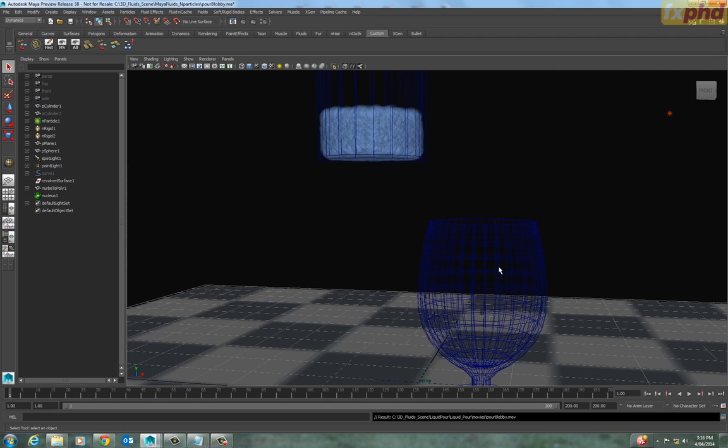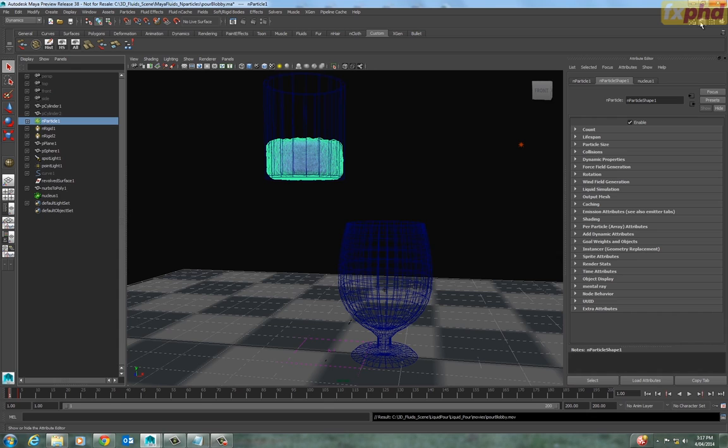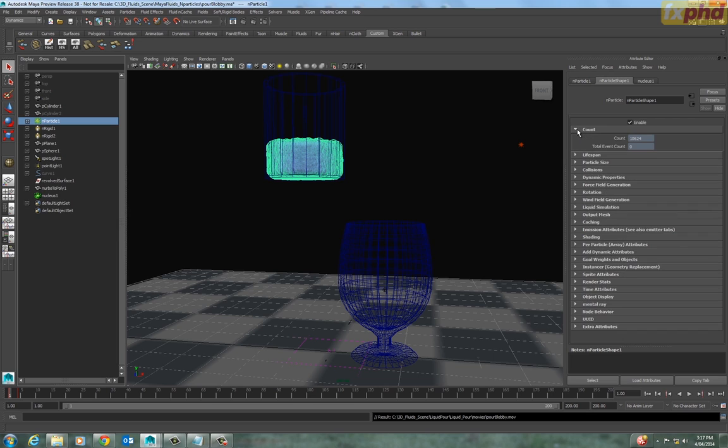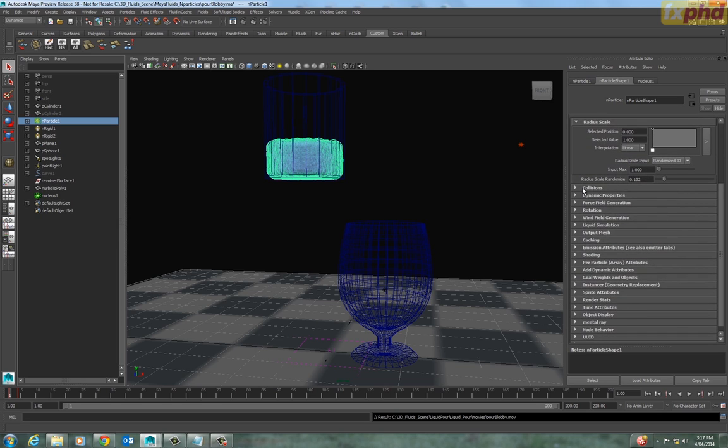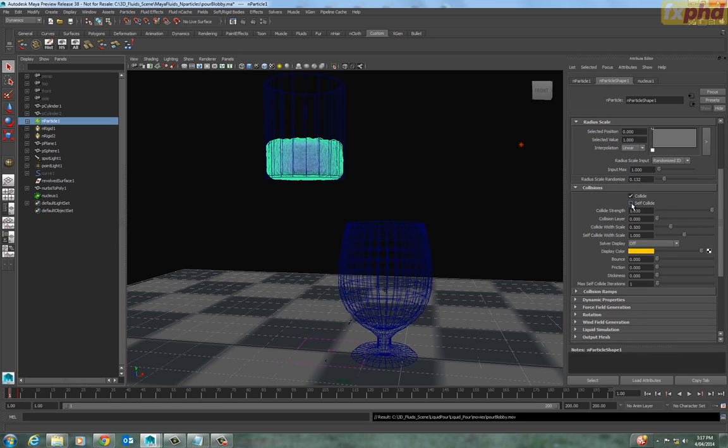This is really different to Maya particles because each particle repels other particles, and you can do real lifelike water simulations when you use the blobby and mesh geometry types for this particle. When we go into this particle, we can see that it's using the new N particle solver instead of the old normal dynamics solver. What it has is just more options for the particles to self-collide, and keep in mind that each one of these new options will increase the simulation time for the particles.